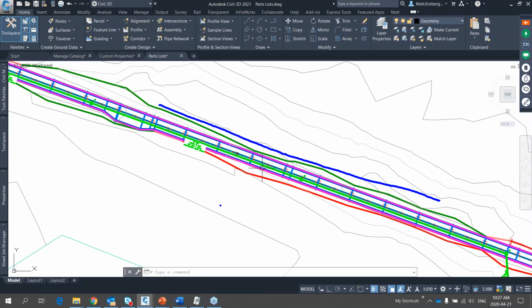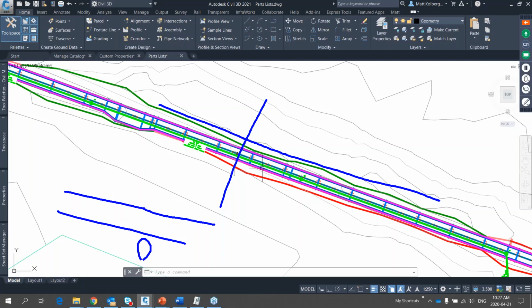Now, sometimes you're going to have a pipe that's, for the most part, perpendicular to your alignment. And you have to show both of these pipes in profile view. And for now, it's pretty obvious how they should be displayed. Okay, in profile, the one that's parallel to the alignment needs to look like that, and the one that's perpendicular needs to look like that, like an ellipse.